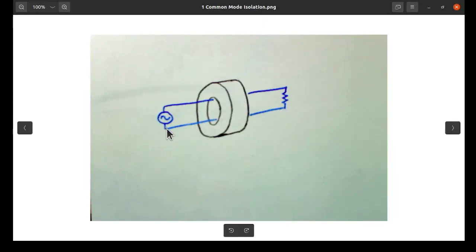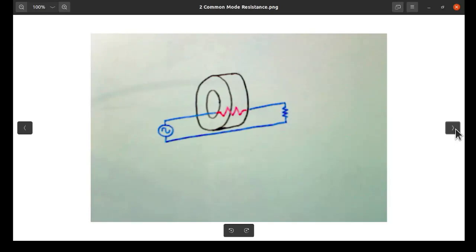as I mentioned in an earlier episode, this core has a bulk resistivity to common mode currents, but we haven't any common mode in this representation. This does represent the operation of common mode suppression, but it's done by forcing the loop going through and around and back with just one lead in the interior of this core.